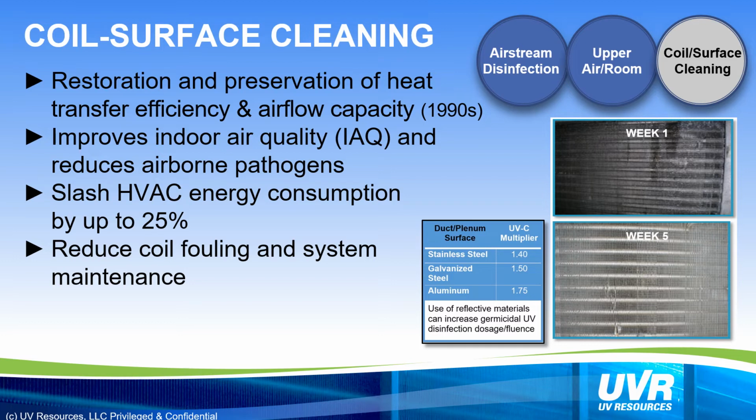Perhaps the most common UV HVAC application is for cooling coil irradiation or coil cleaning systems. These fixtures are designed to destroy biofilm, bacteria, and mold on HVAC coils, air filters, ducts, and drain pans, and prevent these areas from becoming microbial reservoirs for pathogen growth.